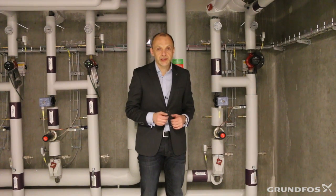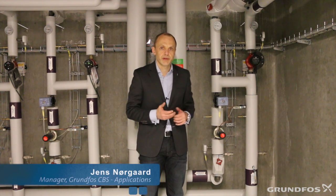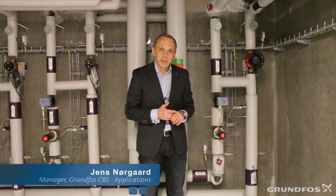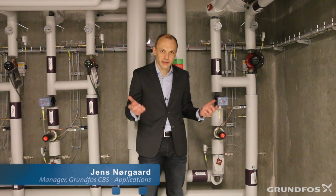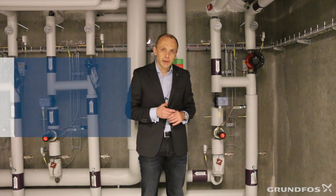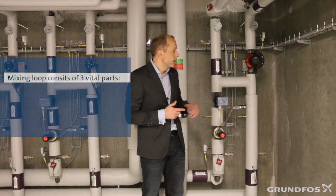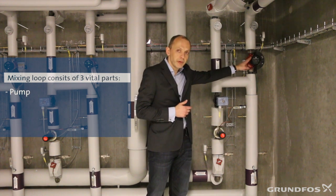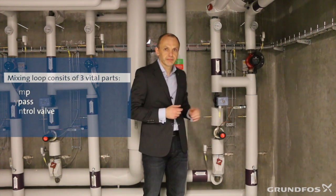The basic functionality of a mixing loop is that it gives us the opportunity to mix up water. And that means that we can mix up whatever temperature we need in a heating or a cooling system. Basically the mixing loop consists of 3 parts. We have a pump, we have a bypass, and we have a control valve.